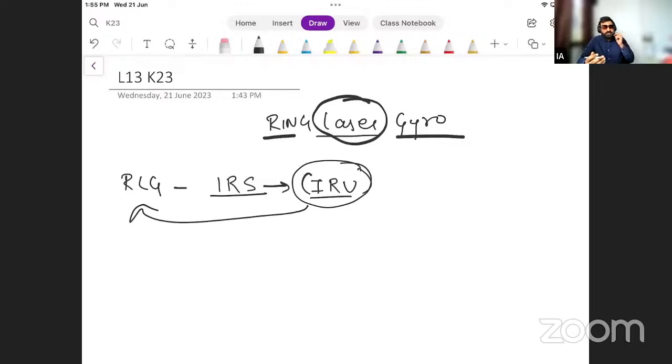With respect to the type of gyro instrument used, we can get a reference with respect to rate gyros, that is, rate of turn indicator and turn coordinator. And then we have attitude indicators that measure roll and pitch angles from a stable horizontal. And then we have directional gyros that give us direction with respect to a stable north.